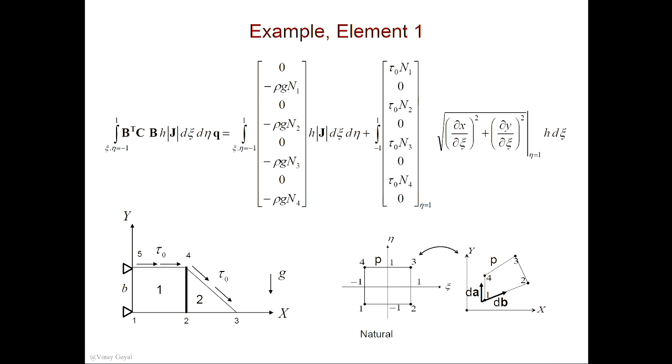And it makes sense because the element formulation for this guy should be 8 unknowns, right? Since I have a quadrilateral, how many unknowns do I have? 4. So I have to have how many unknowns? 8. So it should be 8 in length this way. And this should be 8 by 8, whatever I get here.